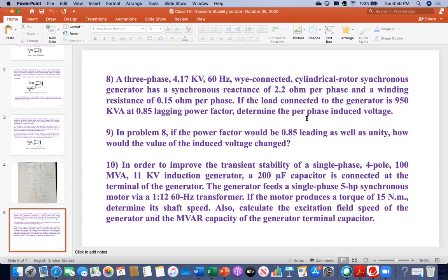Kamana, did you put the angle this time? I'm working on this, Dr. Ali. Okay, so what is the current, Dr. Ali? How much current value did you get? I got 131.53. That is right. That number is right. But what I am saying is, that is your current, but with that current, you have to consider the angle. With that angle, you have to put it in the EA equation, including the angle. And that angle will be minus because of the lagging power factor. True.